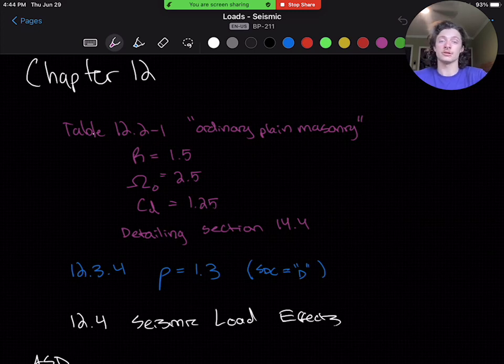And because of the general non-standard nature of this structure, it really should be analyzed with computer software using dynamic time history analysis or modal response analysis. And these are some things we've done in the SAP 2000 software, and is just a more efficient way to do a useful analysis of the entire bridge. However, what I'll go through here is a pretty standard design procedure. It'll get you familiar with the terms and how to think about calculating seismic loads on your structure.